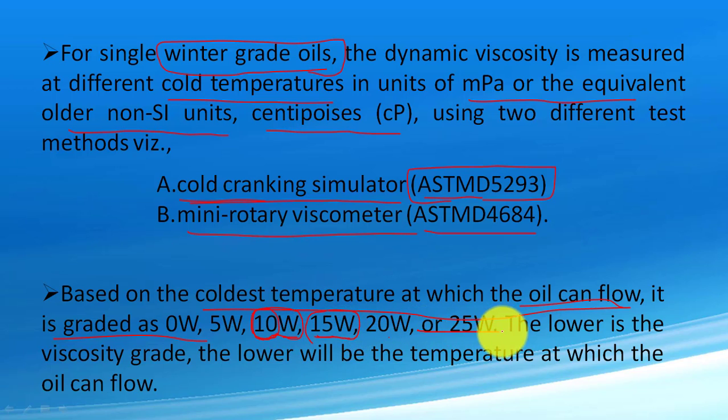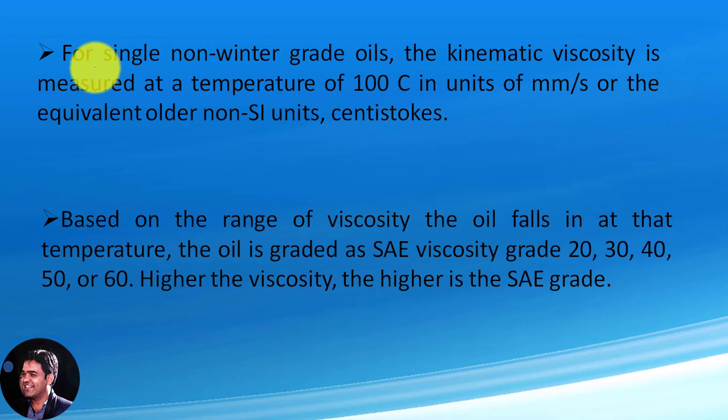The lower the viscosity grade, the lower the temperature at which the oil can flow. So for cold weather conditions, we can go with the lower grades of engine oil. Single non-winter grade oils are designated by a simple number, like 20, 30.